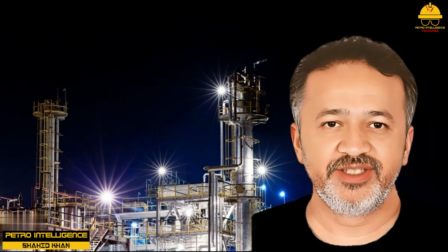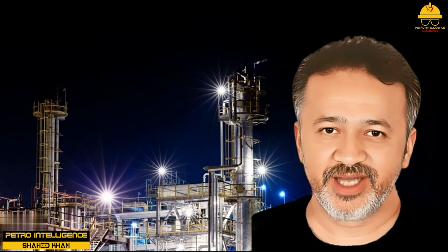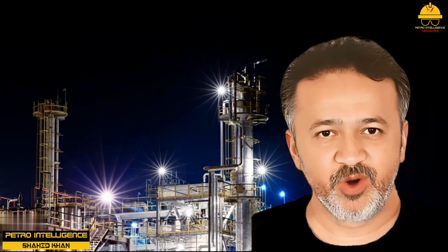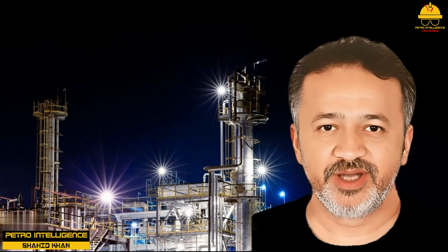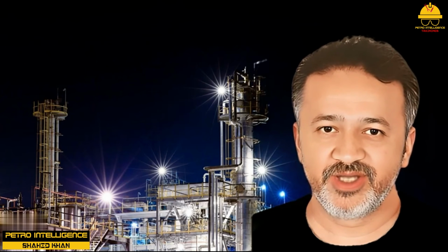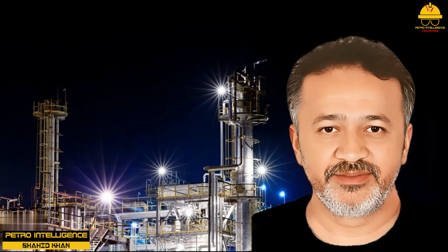The basis for such a decision is concerned with 1. The availability of steam, brine, cooling water, and the like, 2. The temperature at which the reaction must be controlled, and 3. The cost of each method per pound of production.